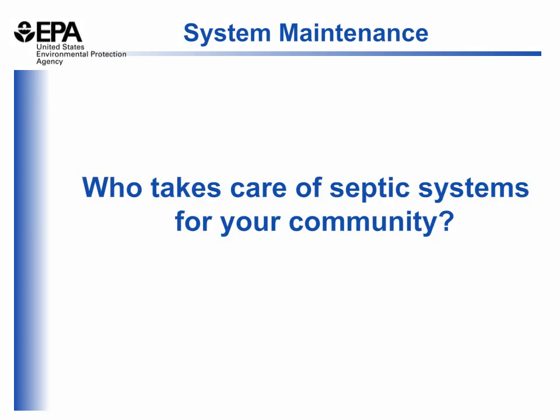As you think about septic system management, who is it within your tribal community that takes care of on-site septic systems? In the presentations we've done in different parts of the country, we've seen a variety of different models in terms of who is managing on-site septic systems. In some cases, it's the homeowner that's responsible for taking care of their own system. For other tribes, the wastewater treatment plant operators may be tasked to also take care of the on-site septic systems for houses that aren't connected to the centralized facility. In this case, they do occasional septic system inspections and manage the pumping or the fixing of the systems on a needed basis.